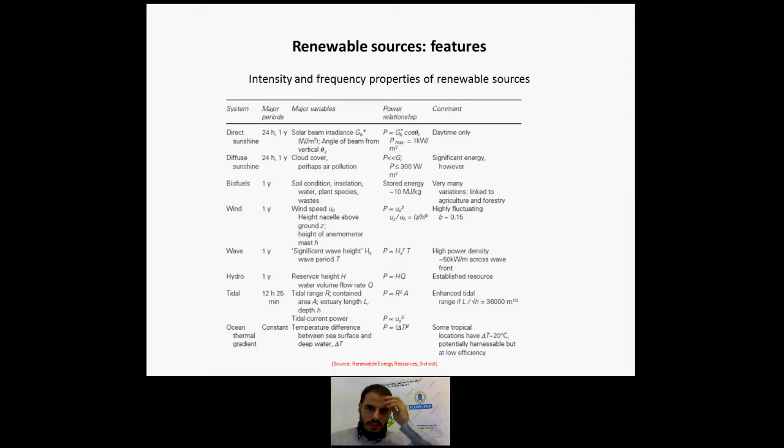usually given by technology uses for the purpose, is due to seasonal variations in most renewables options. The resource has to be monitored for at least a full year at the site in question, because not every site has the same characteristics. For large-scale projects, for example, if it is hydro more than 100 megawatts, a decade or more of data may be needed. Ongoing analysis must ensure that useful data are being recorded, particularly with respect to dynamic characteristics of the energy systems plan.